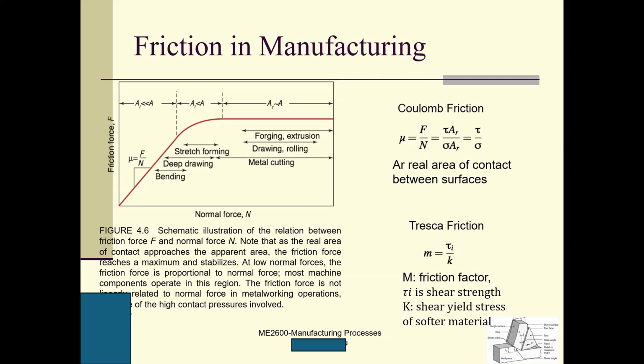Sigma 1 minus sigma 3, then take the absolute value. If this absolute value is less than a critical value, it's okay, otherwise it fails. It's called Tresca. The second one is the von Mises criterion. The von Mises criterion is more complicated. It's an equation there. So this is the second time we see Tresca.